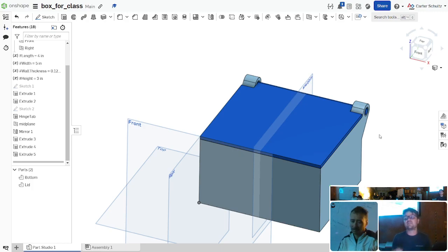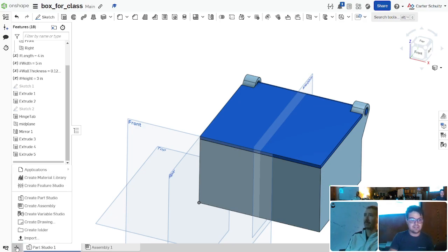And the drawing includes more information than the actual model of the part does, and that's where you put a bunch of tolerance and manufacturing specifications and paint color and so on. The world operates on drawings. OnShape has a very good system for making drawings. So down here in the project, I can do insert new tab.